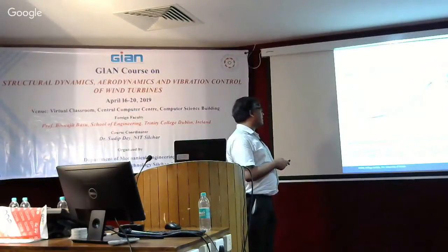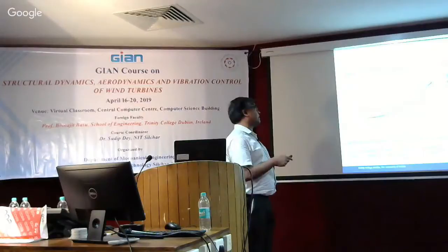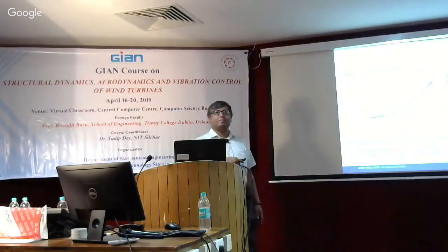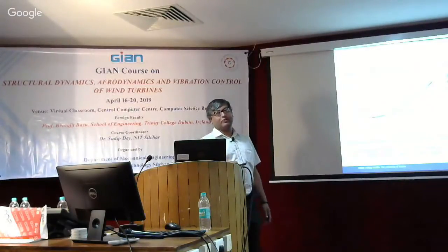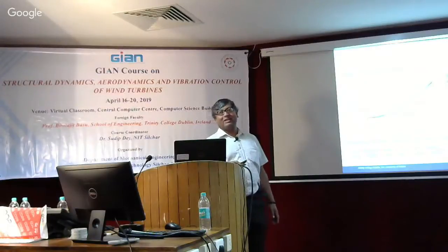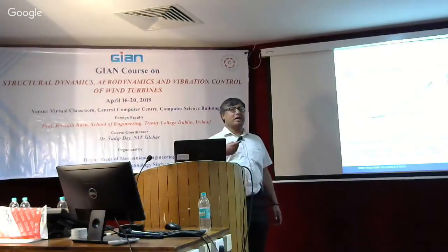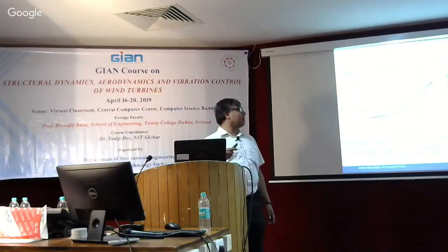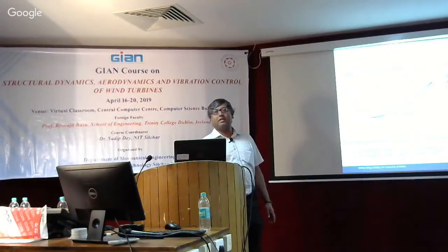So these are the mode shapes corresponding to the first and second modes. Now this blade has a pre-twist, so there's no pure bending mode actually. The first mode will have some component in the edgewise direction, and the edgewise mode will have some component in the flapwise direction.